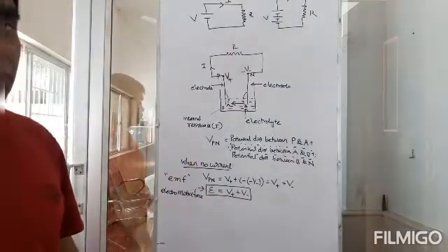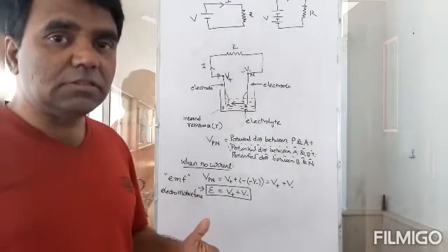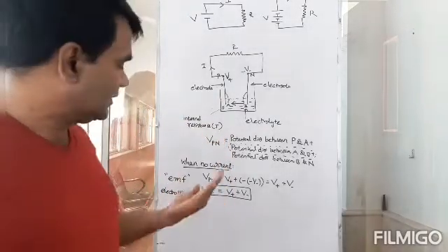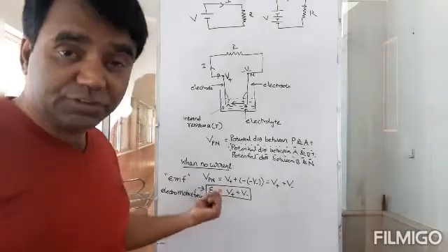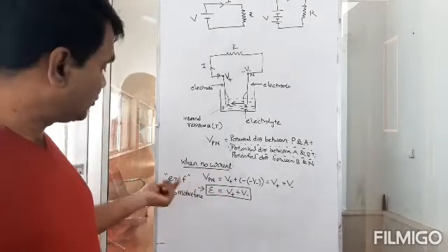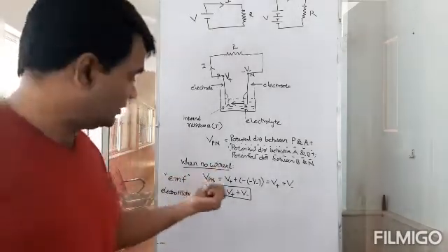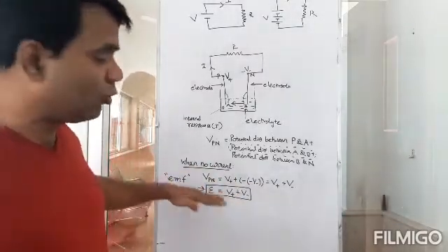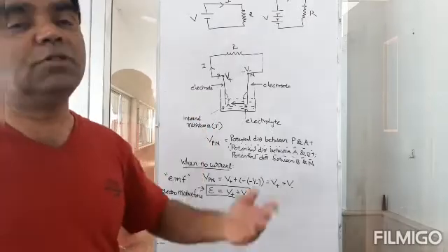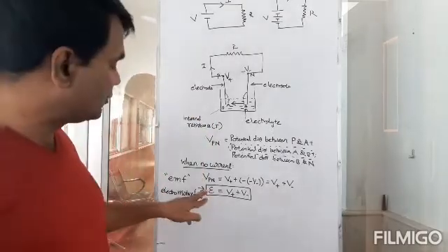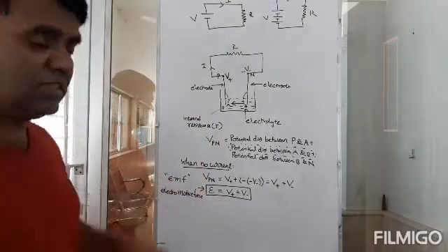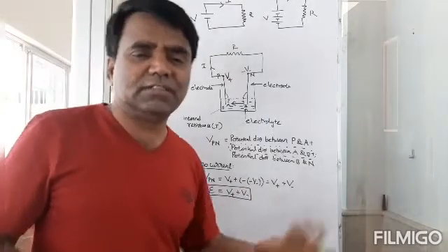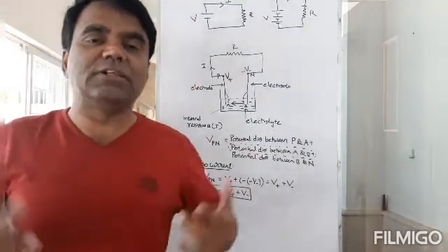Okay, but it is not a force. This is a potential difference. So this is not going to be measured in newtons. Even though you're calling it a force, it's not a force. It is potential difference. So this is in volts or joules per coulomb. Then why do you have this name, electromotive force? That's because of historical reasons.